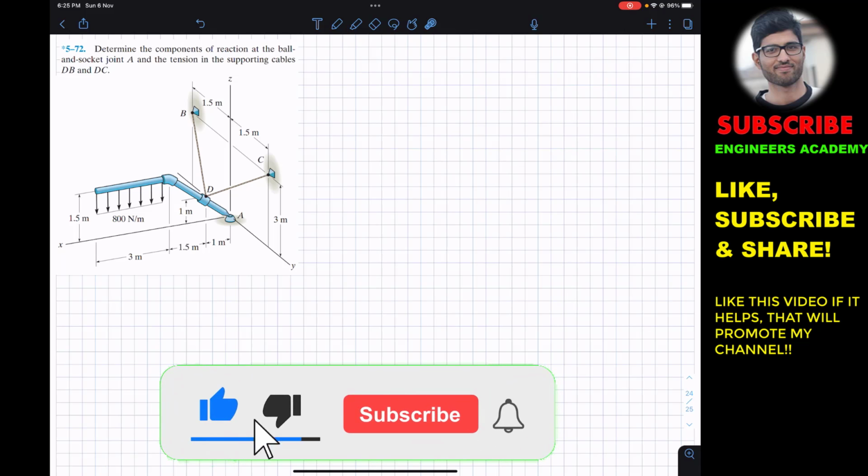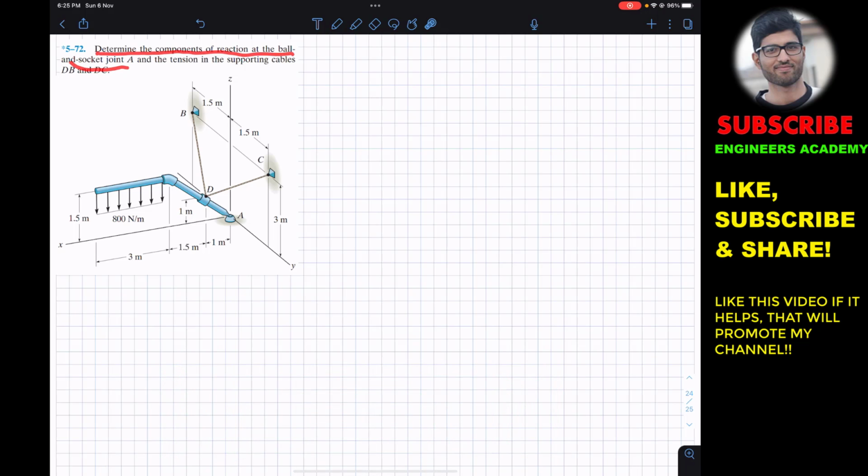Now let's solve this problem which says: determine the components of the reaction at the ball and socket joint at A and the tension in the supporting cables DB and DC. So here we have at A the ball and socket joint. The ball and socket joint can provide the reactions along all three axes. So we will have AX reaction, AY reaction, and AZ reaction. So we are required to find AX, AY and AZ.